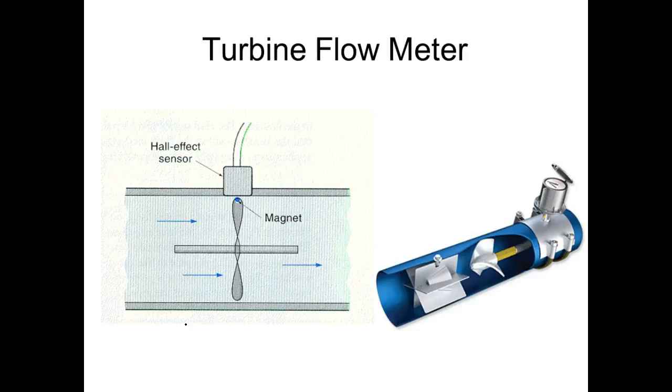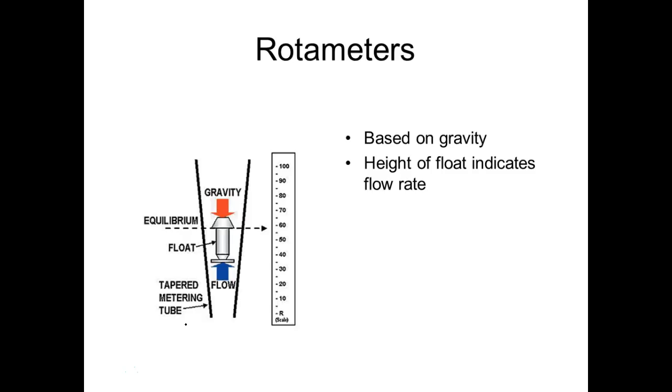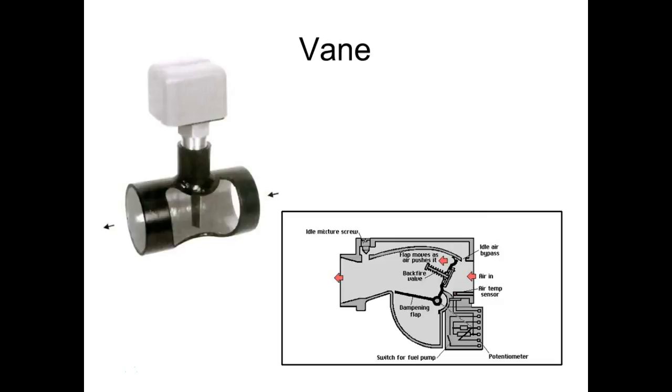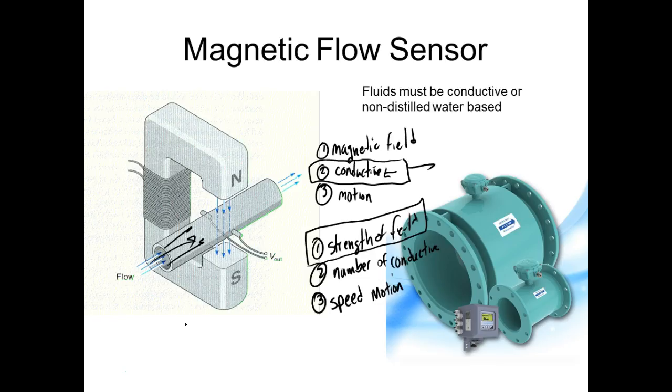But the problem is, if I had a fan and I took my air compressor out and blew the fan, if I measured the pressure on this side and the pressure on that side, it would be different. So every one of these basically creates a pressure drop. This one right here has no opposition. You measure it both directions. Yeah, well, a lot of them you can measure both directions.